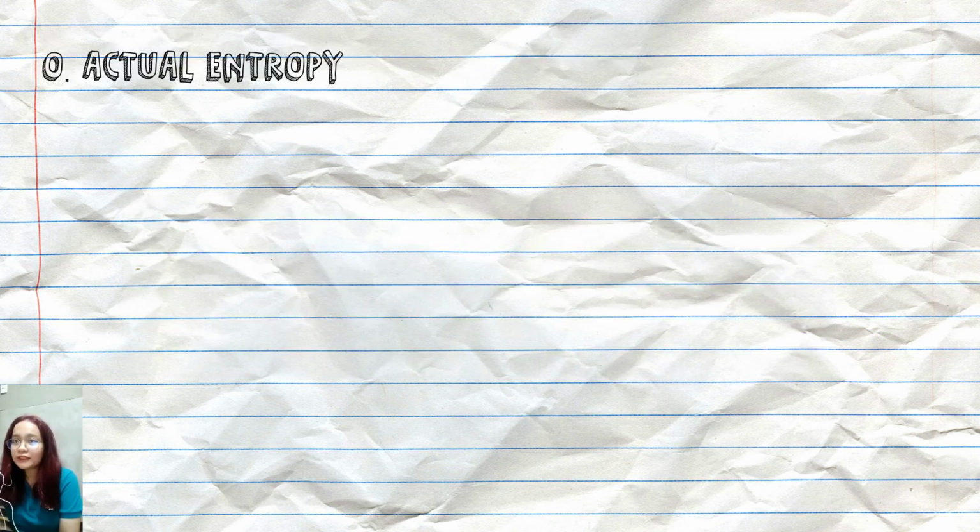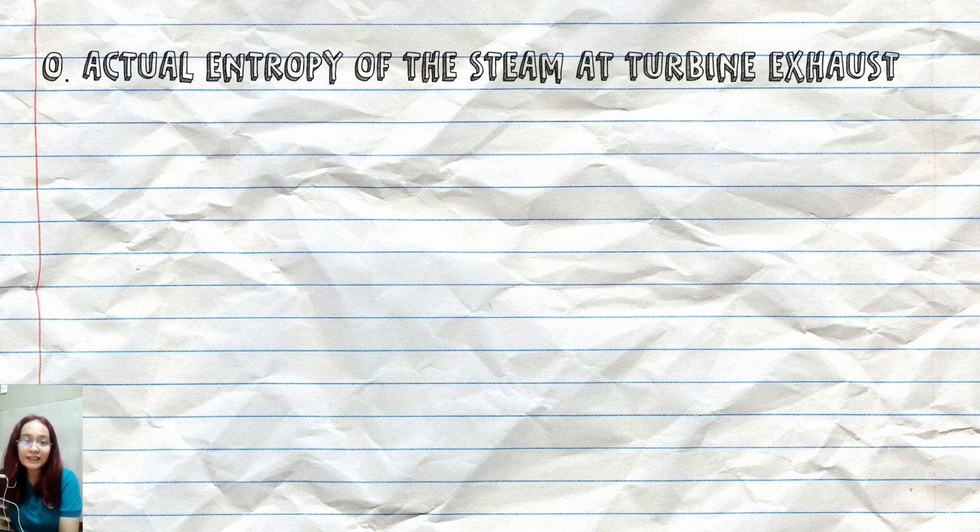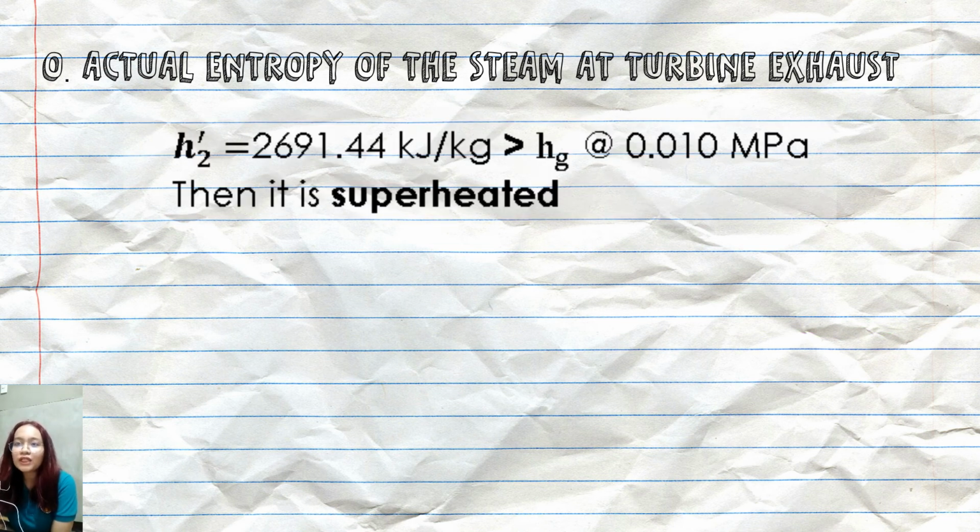To find the actual temperature of the steam at the given exhaust and the actual entropy of the steam at turbine exhaust, we will be doing interpolation. From the previous solution, we have seen that the actual enthalpy at point 2 is 2,691.44 kilojoule per kilogram, which is greater than the specific enthalpy of the saturated vapor, which means that the condition of the steam is superheated.